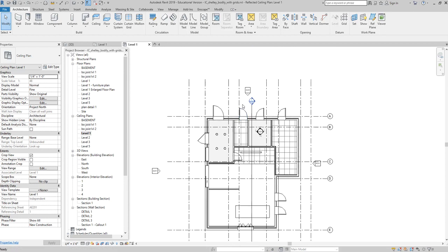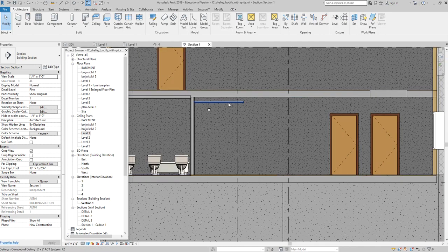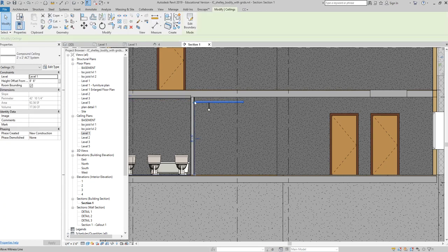And I'm going to do that. I'm going to drop this little hallway. I'm going to make this a soffited area, okay? So right now my ceiling, if I click on it in sectional view, is 8'6", and I want to make it 7'6" above level 1.